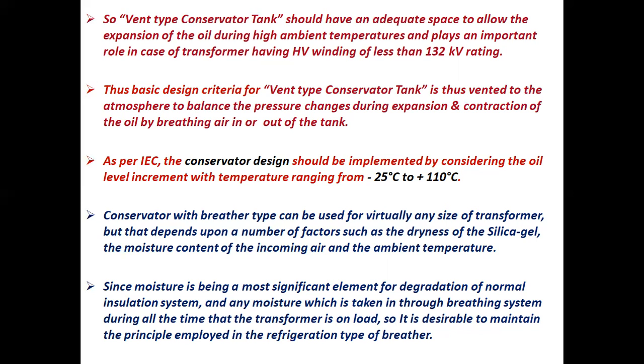A conservator with breather type can be used for virtually any size of transformer, but that depends upon a number of factors such as the dryness of the silica gel, the moisture content of the incoming air, and the ambient temperature.